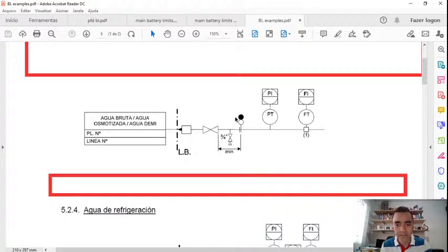And there is here, you can see that there is a figure here, two circles, and one is black and another one is white, and a trace here, and it means that we have a figure 8. And the figure 8 is a kind of hack that is used to guarantee the full isolation of the valve.